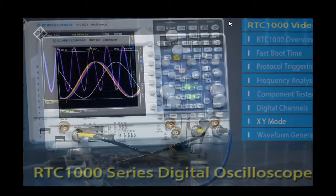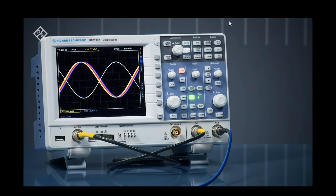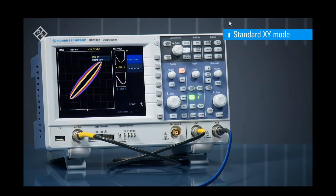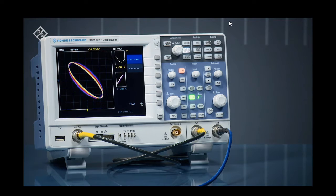R&S RTC1000 series oscilloscopes feature a standard XY mode. Plotting two signals against each other allows you to view the relationship between them, in this example a phase shift. In addition, small preview windows let you easily control the settings of your waveforms.